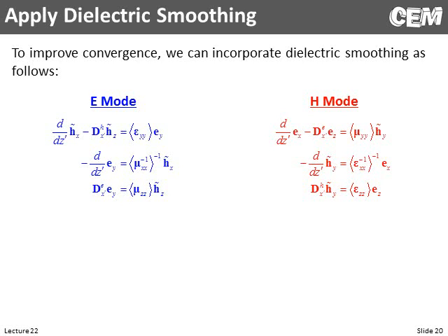So in place of our standard epsilon matrix, which is a diagonal matrix, I wrote it with these little triangle symbols here, meaning that this really is the original epsilon YY, but blurred by 1 pixel, just to slightly blur and average the material properties at the boundary. So we do that for both the permeability and the permittivity.